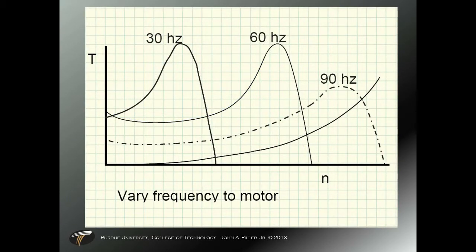Here's a graph of the torque output of a motor with a variable frequency. As you can see, the power out is decreased at lower than rated frequencies and increased at higher than rated frequencies. Again, the parabolic up-shaped curve is a representation of the load curve. There is compensation we'll need to deal with for the lower frequencies versus higher frequencies. But first, let's look at a completed block diagram of our system.